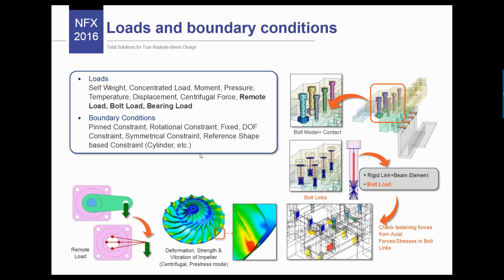On this slide you can see all the loads that are available. Not only the simple normal loads like force, pressure, self-weight and all that, but also a bolt load, a remote load or bearing load. This kind of thing is very important to simplify the modeling and do things faster.